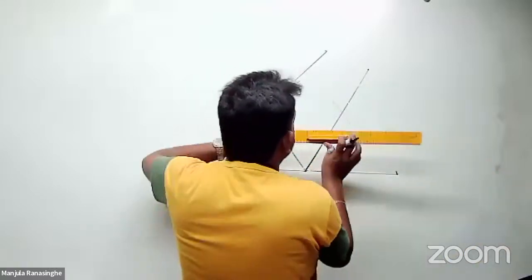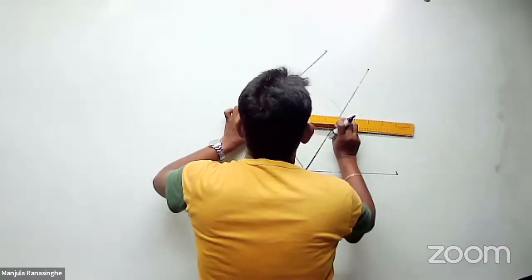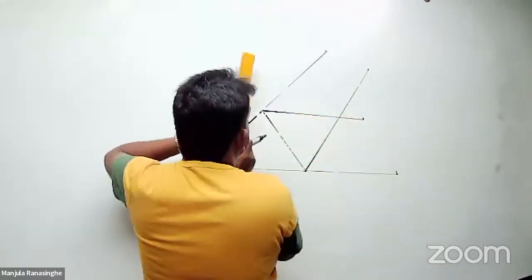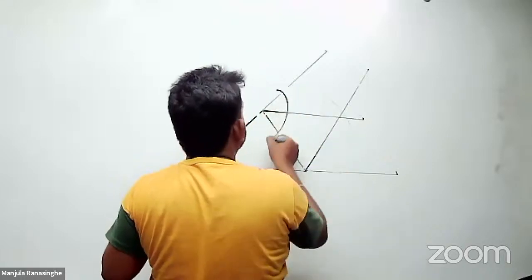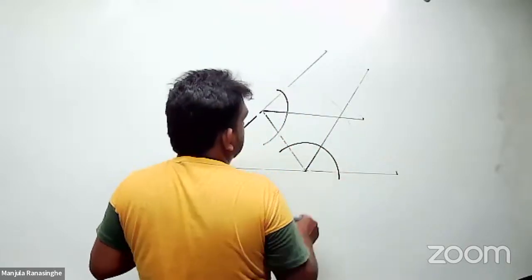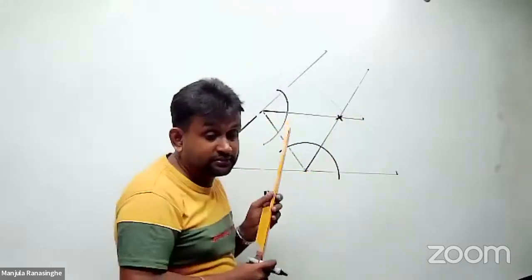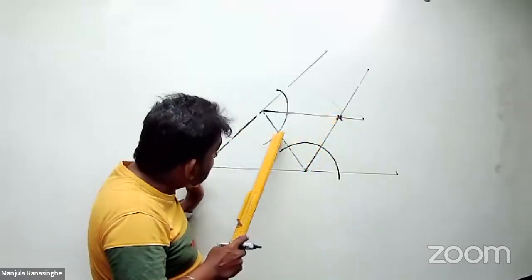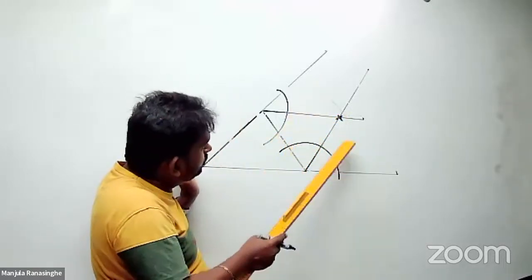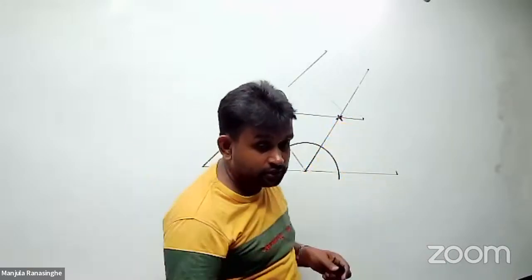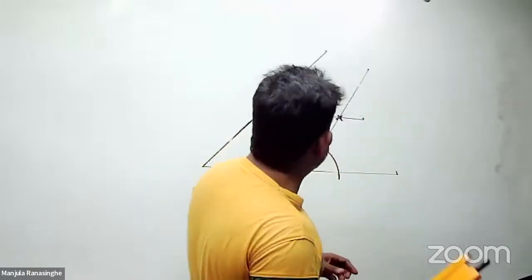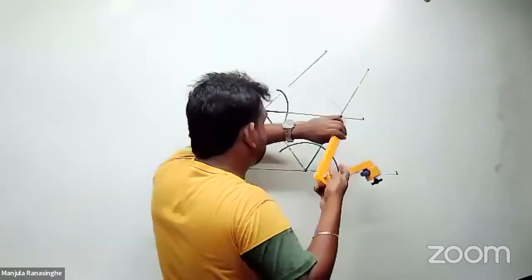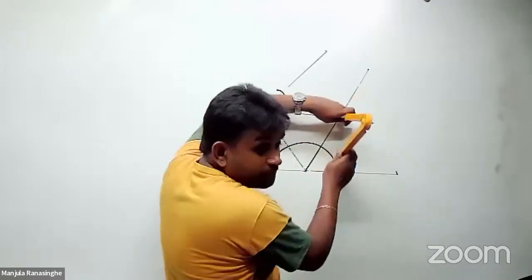Then I draw it for you. So this is the angle bisector here. Now this angle is drawn and this angle is drawn. Now this is the center of the circle. Now from the center to any side or extended side, you draw a perpendicular. We have to draw a perpendicular from here to any side. So of the extended sides, I draw a perpendicular to an extended side.